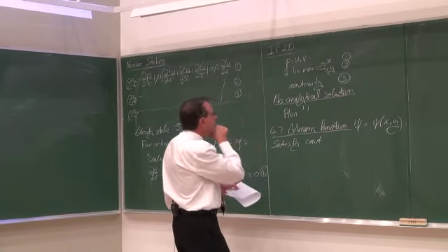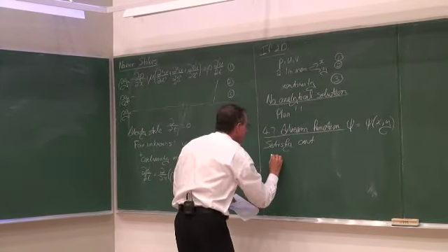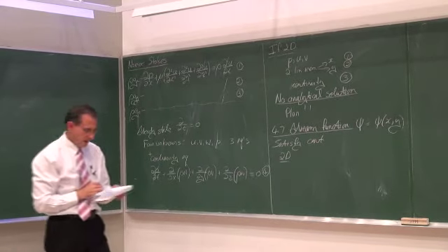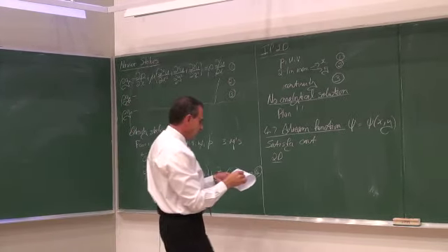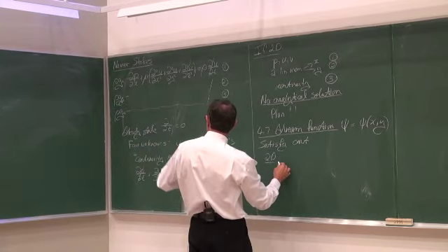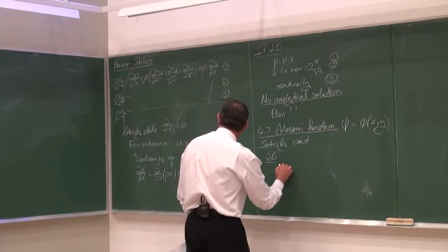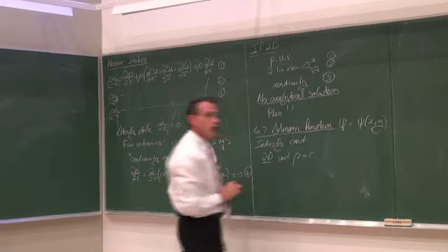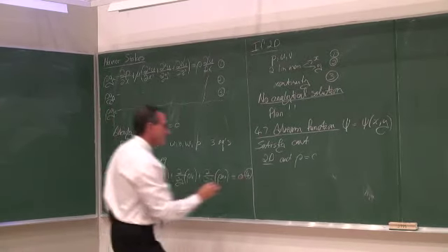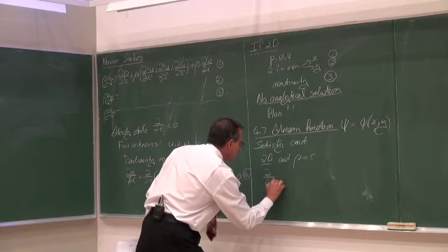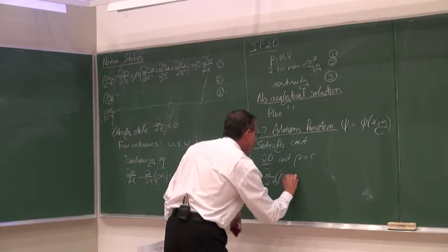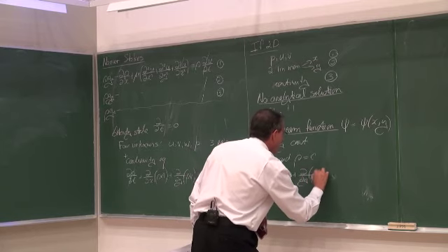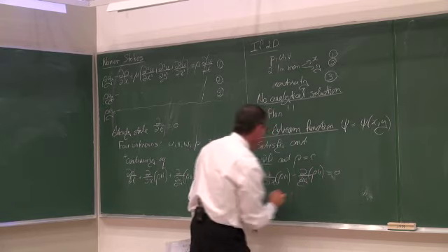So if we now look at the two-dimensional case, so we make the assumption it is two-dimensional, and we look at the continuity equation, and we say that rho is equal to a constant, then ddx of rho u plus ddy of rho v is equal to 0.